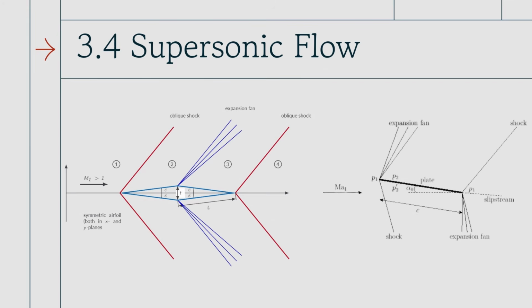But as soon as you start to actuate them in different directions, what you create is the second photo here on the right, where you get a shock and expansion fan pair at both the front and back of your canard. That can add drag to your vehicle. It can create some funky loads. To be honest, I'm not super familiar with what it actually does, but it's wonky.